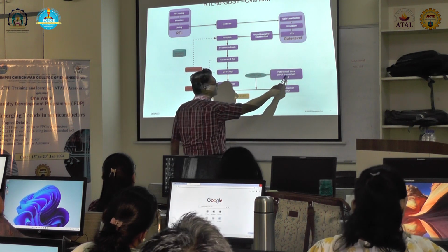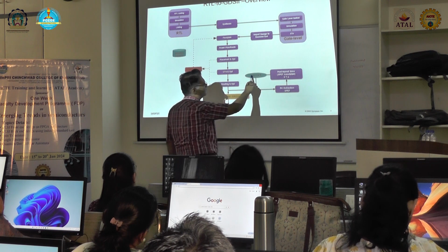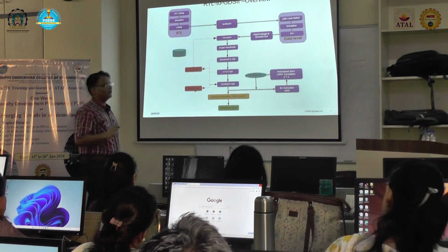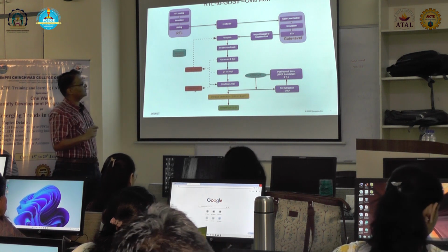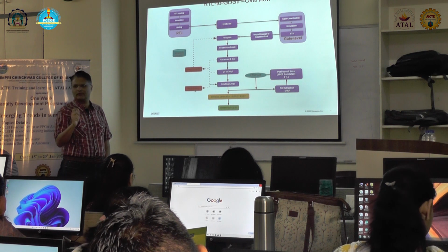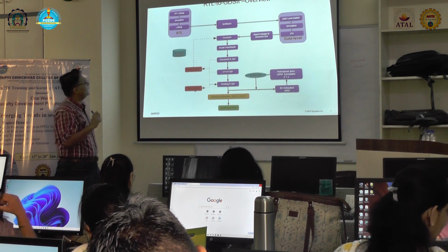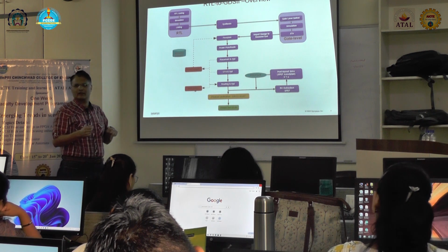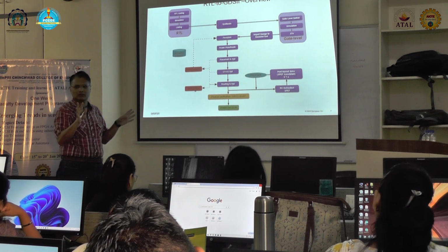If the circuit does not work as expected, we have something called an ECO, which means engineering change order. ECO full form is engineering change order, and we perform a gate level fix in the netlist. We don't modify the RTL anymore.